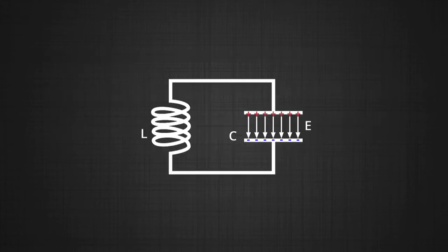So, look at this diagram, what do we observe? Here we have an inductor and a capacitor. So, what is happening here? The charge flows back and forth between the plates of the capacitor, through the inductor. The energy oscillates back and forth between the capacitor and inductor until internal resistance makes the oscillation die out or vanish. In most applications, the tuned circuit has alternating current applied to it, driving continuous oscillations.